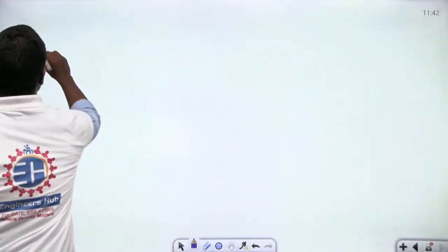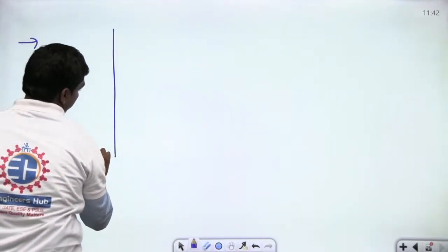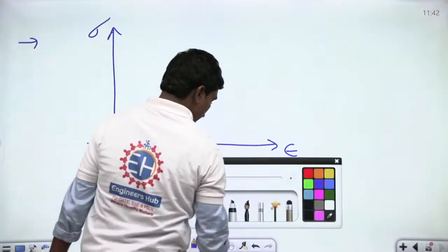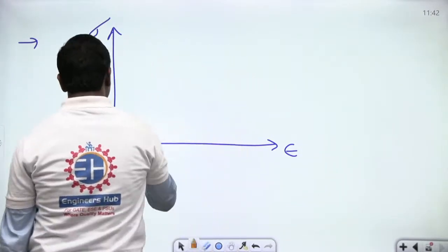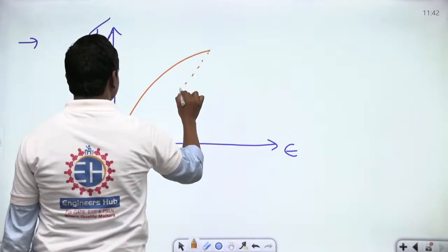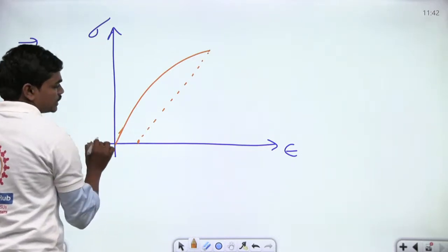Yes, there is some material which is stretched beyond its elastic limit. In the stress strain curve, you could see some curve or some property of the material like this. So basically, there is some stretching of this material, and of course, when you unload, it traces back along this path, which is parallel to this initial portion, correct?